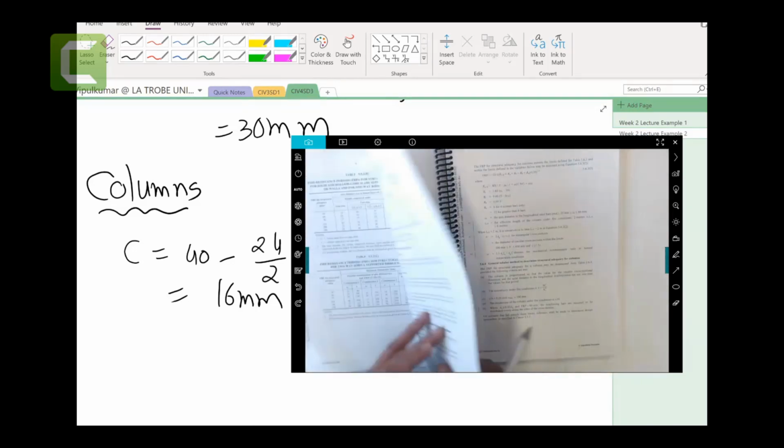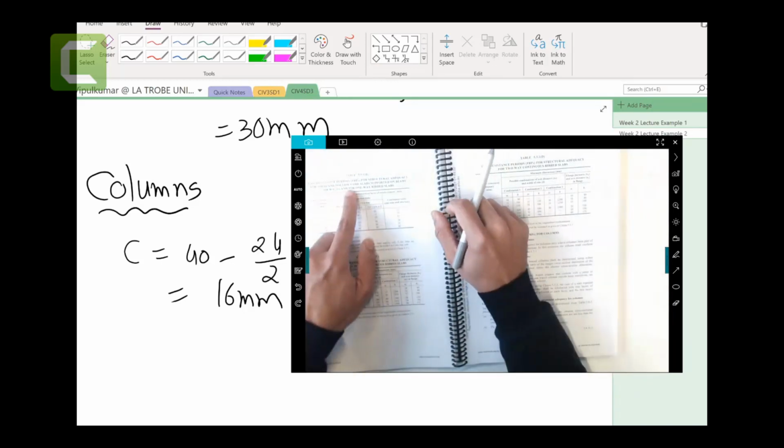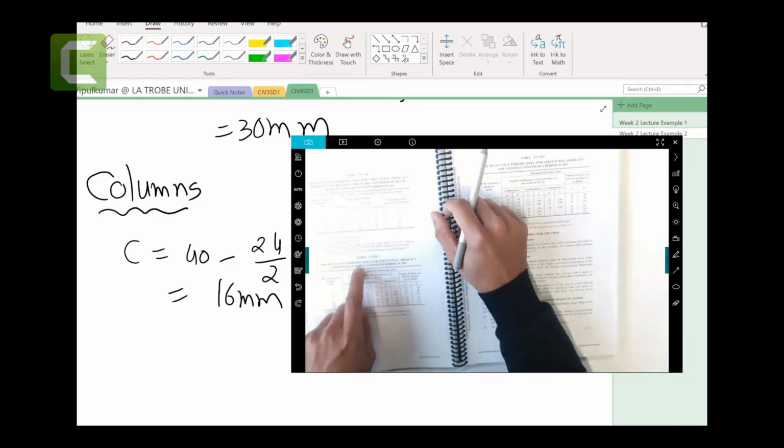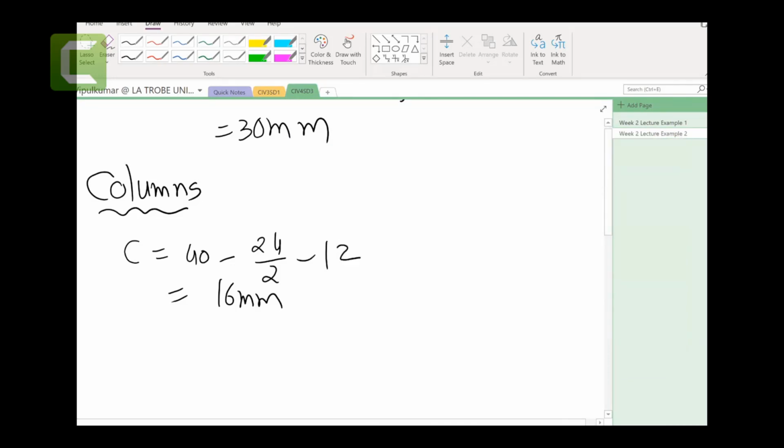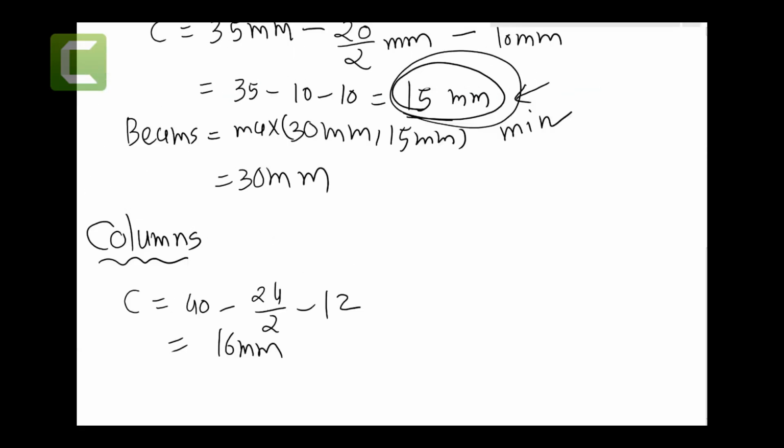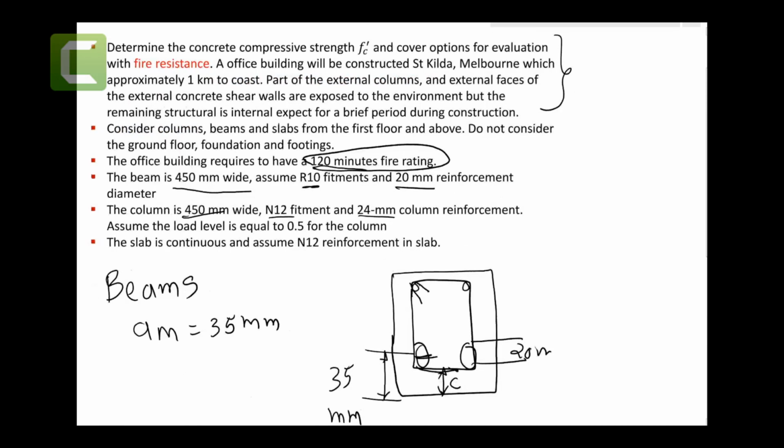I think we need to make an assumption saying which kind of slabs we want the fire resistance for: structurally solid and hollow core slabs, or we want to have two-way simply supported rib slabs and so on. Based on, I think in our examples is given. Continuous, the slab is continuous. So probably continuous and one-way slabs. So let me check if there is a one-way slabs and all. So you have these one-way slabs here, and for that one-way slabs,